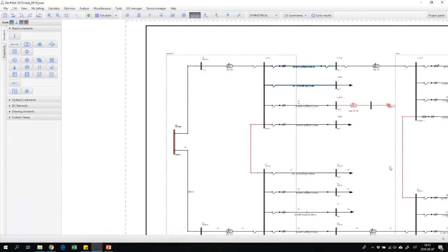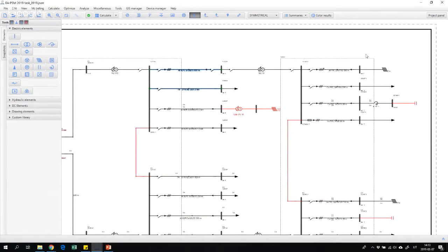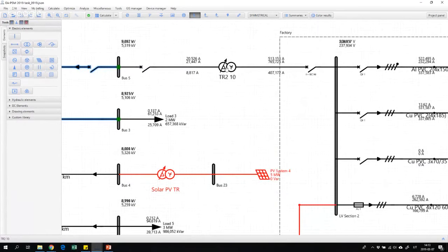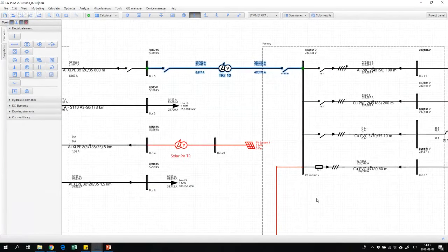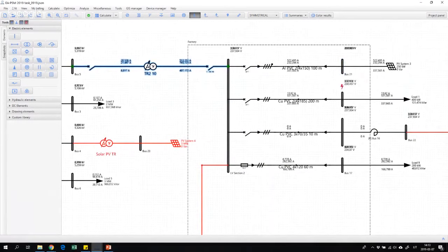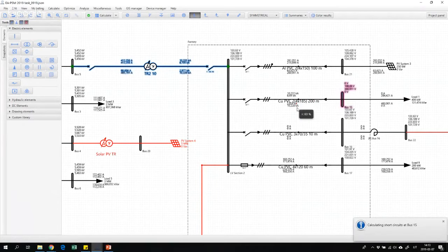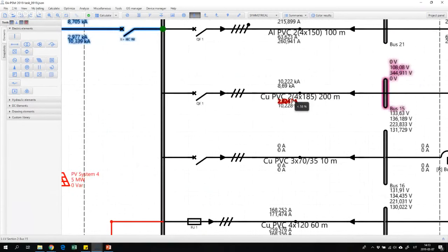However, if we go to a grounded neutral network, here by the way connected with two transformers, in this kind of network our currents, in case of one phase short circuit, will be much bigger. So you can see it's around 3000 amps.